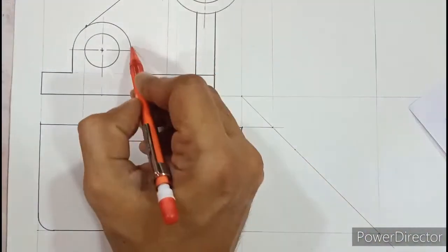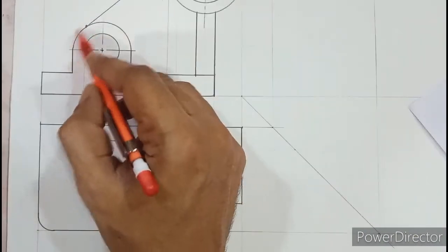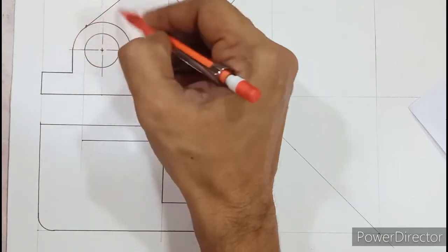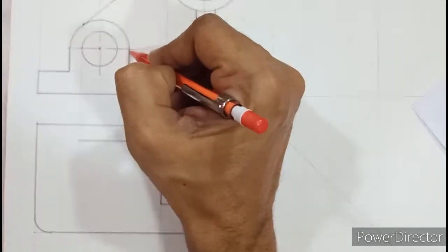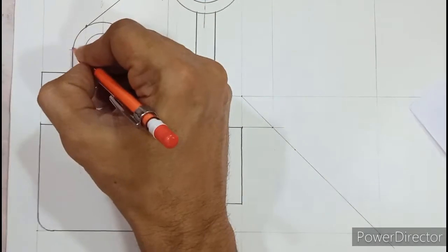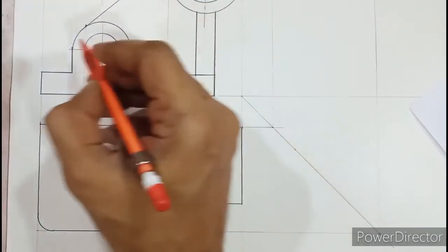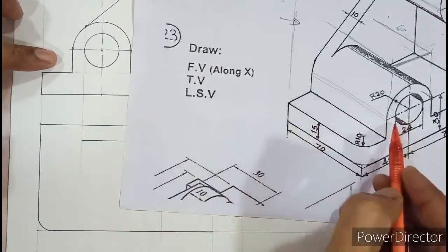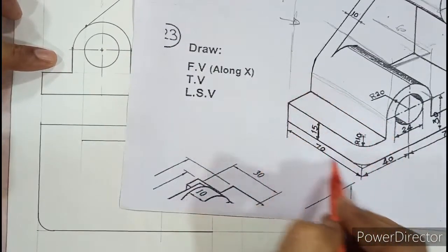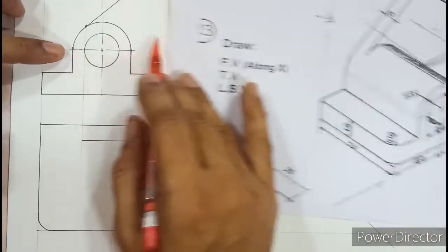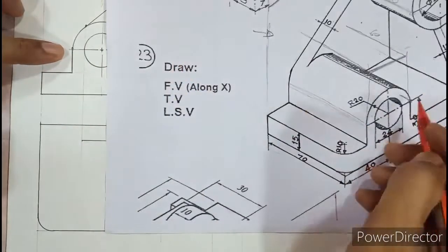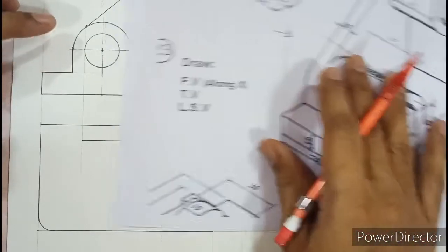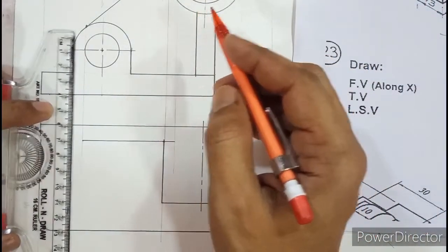So this is the semi-cylinder part, right? So at the top, from top view when you observe, and if you project parallel rays of light, you can see only this part of the cylinder which is illuminated. So both the boundaries need to be projected down. Now carefully look here. The left side boundary, that is this one, will be seen up to 70 millimeter. This is 70, so this will also be 70. Whereas the right side boundary on the other side is not up to 70 because there is a rib in between. So you can see only up to 60. So let us project these 2 points.